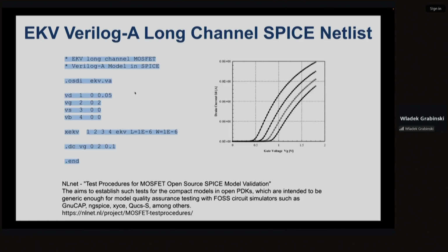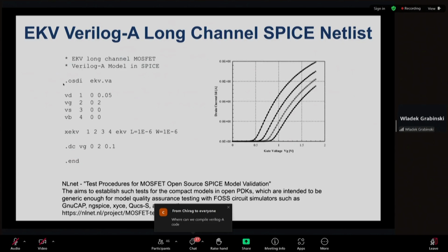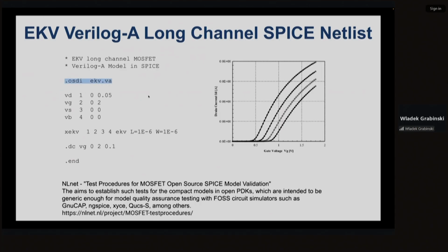On the left, you have a very simple input deck to simulate transfer characteristics. All you need to do to call a Verilog model is to have one extra statement. So this task is fully transparent to a designer or ngSpice user.